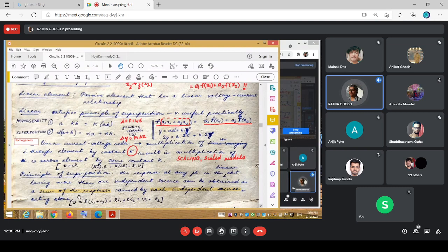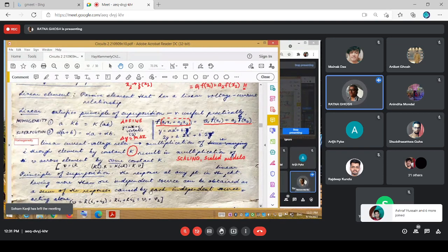That if you need to augment, which is exactly the principle when we use batteries. You need a 6-volt supply, you put in one battery. You need a 12-volt supply, you put in 2 batteries in series, and so on and so forth. How can you do that? Because this superposition holds. You can disregard the effect of this one.